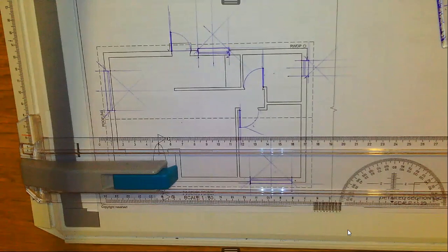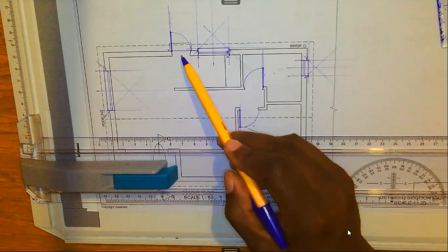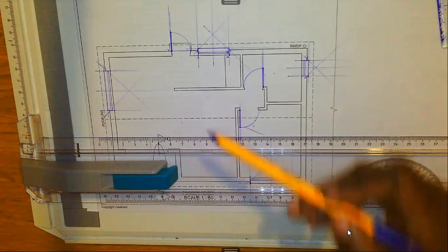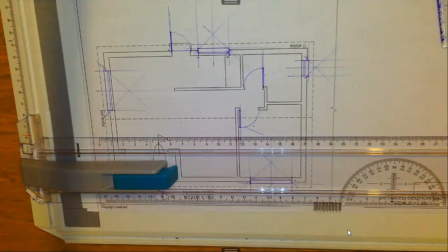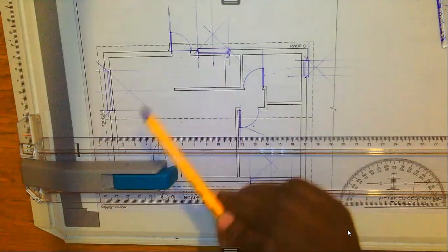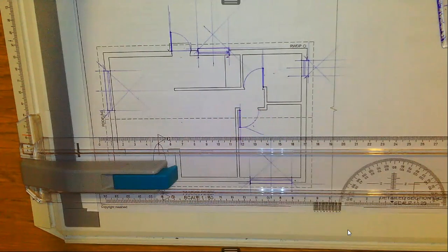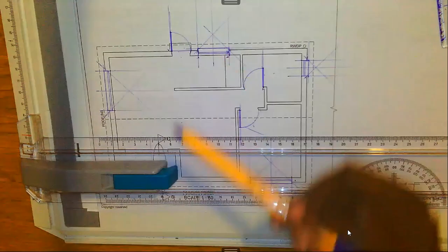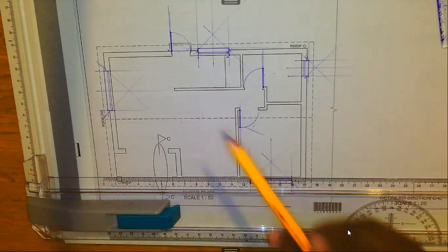Yes, of course, you'd find that in some cases, as long as you are now at the veranda stage, the level is basically the same. But still, in some cases, you'd find that the levels are different. Just to be on the safe side, as long as it is an external door leading to the outside, draw that line, in case it is allocated a mark in terms of the rubric. Right, we are done with this door, and that door, okay?